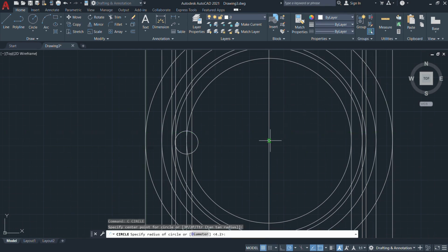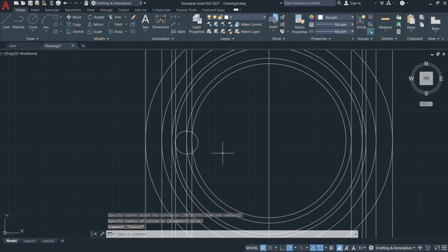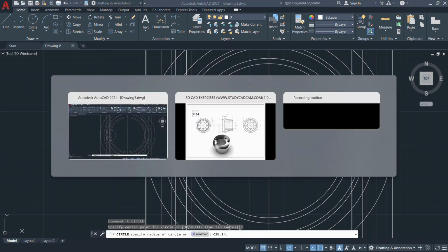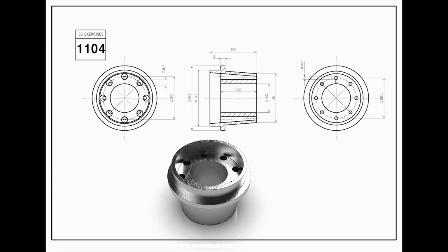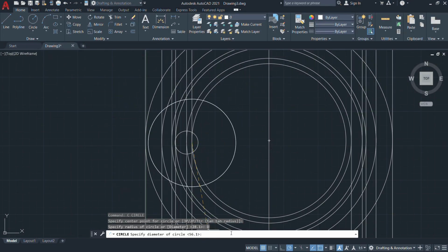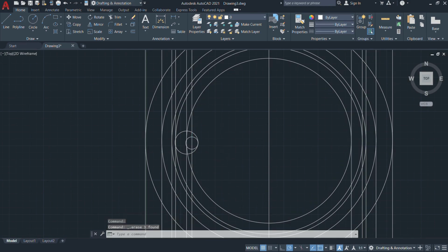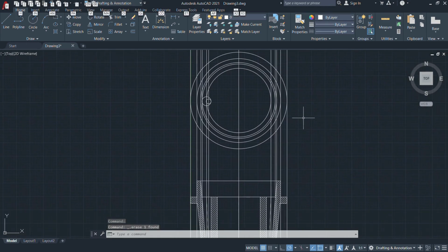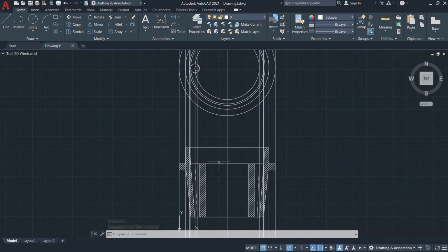Okay, now from the center point, I just draw one reference circle tangentially meeting this vertical line profile and draw another circular profile from the same point. It represents a 4.5 mm diameter. Only mention a diameter of 4.5 mm. It is placed properly. Then delete it because it is only for reference purposes. Now one of the profiles is drawn. Look at it. Almost all profiles are drawn.